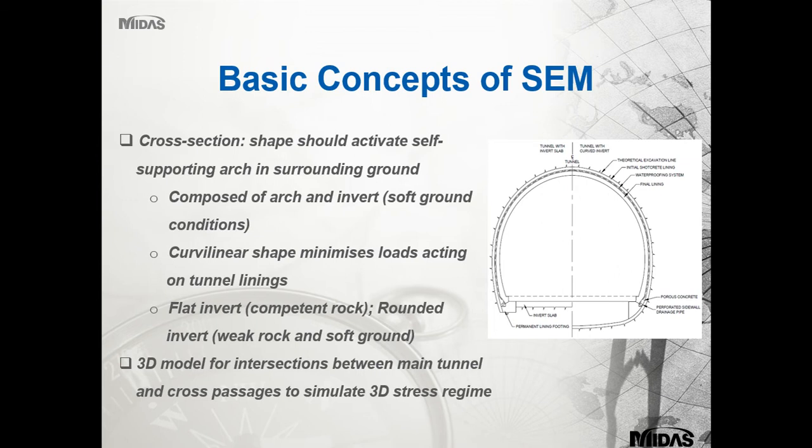A curvilinear shape minimises load acting on the tunnel lining. This is the arch effect we're always talking about, often used in bridge structures as well, where it will take load away from the actual tunnel lining itself, depending on the angles and the arch form that you've used.